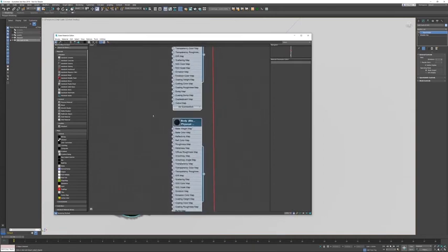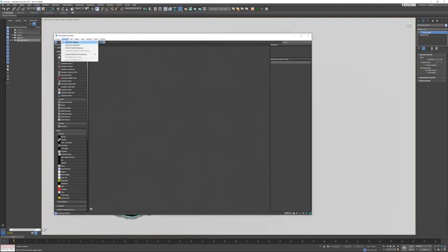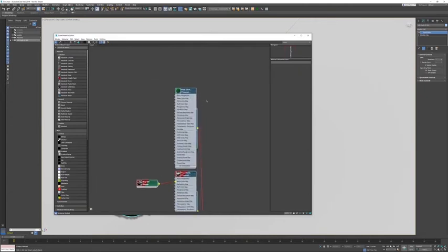The old materials are still in there, but they are disconnected. So if you want to just clean it up, go into edit, do a clear view, hit yes, and then get it back from the selection. There it is. Okay, so now it's corrected.